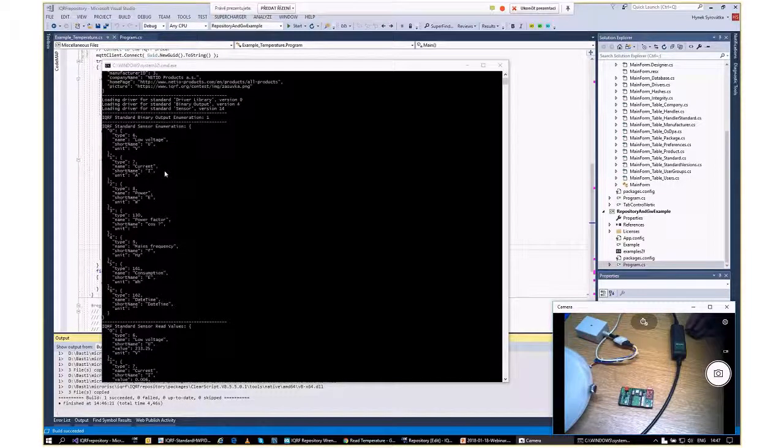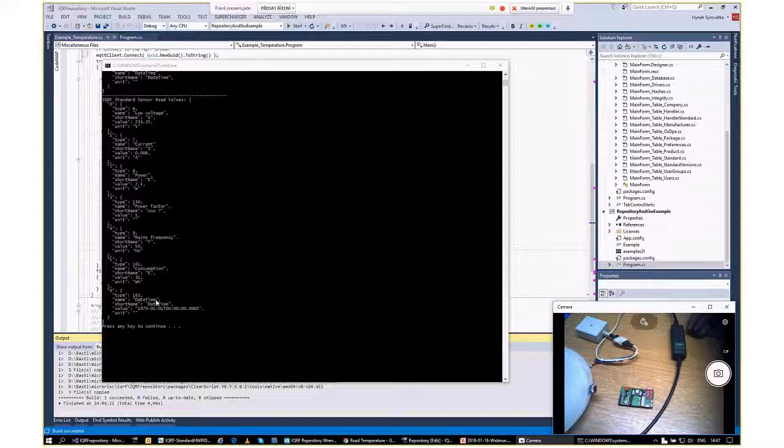Here you can see the difference compared to what I showed you in the IQRF IDE. The IQRF IDE had to understand the response because it cannot use drivers yet. Here we use the drivers. So when I asked what are the values and the sensors of this plug, I got a result like this. I simply got an array of 7 objects. Each object gives the details about each of the 7 sensors. For instance, the current: the name of the sensor, type is number 7. This is a standardized type in our standard. The short name is I. The value is 6 milliamps, and the unit is ampere. Yeah, the same with the frequency, the same with the power, and so on and so on. So this is it. This is how it looks and how it works.